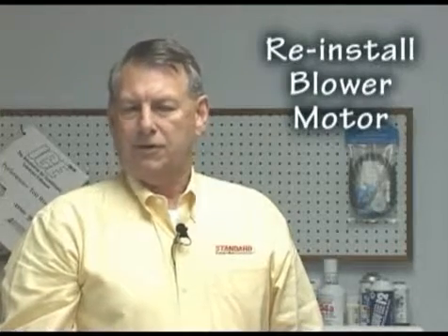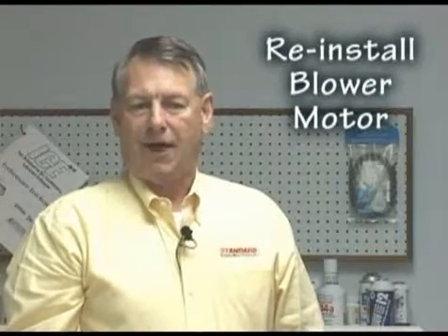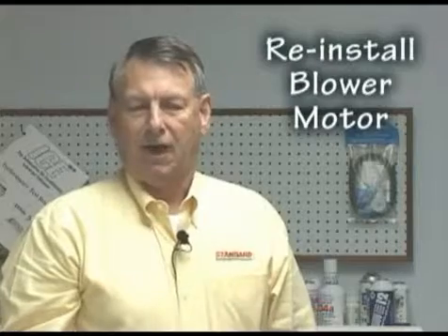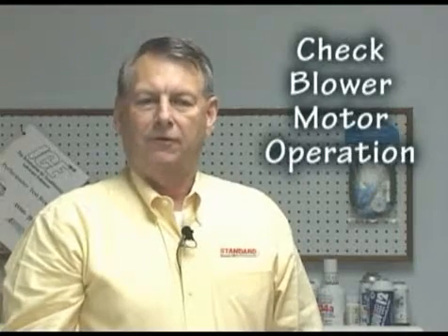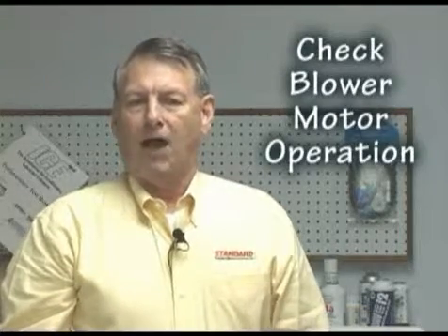There are no TSBs. We purchase a blower motor control module and install it in the truck. We reinstall the blower motor, turning it clockwise until it latches under the locking tab. Cycling the blower control switch on the control head from low to high, returning to high, returns it to normal operation.